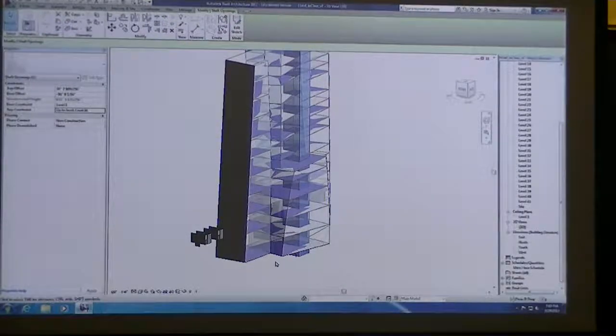Because look down, look into your 3D view. By default, if you didn't set anything, it only went up 20 feet. So go all the way down to your first floor, and you have it selected right there. You can see it in blue with the drag handles. So now if you look to the left, yeah, you can move that up and start to manipulate it from there.